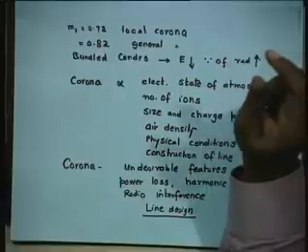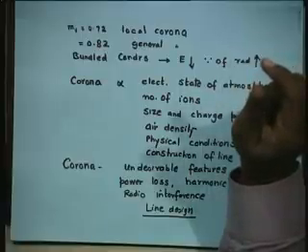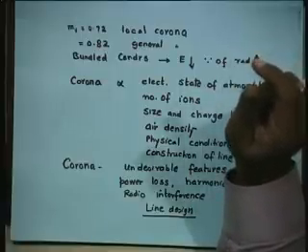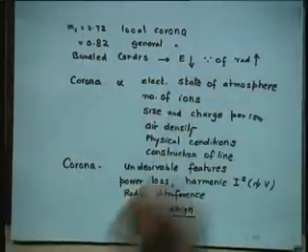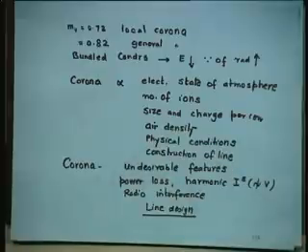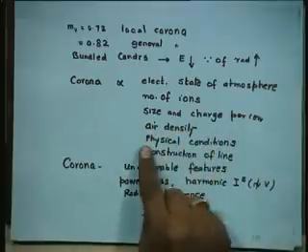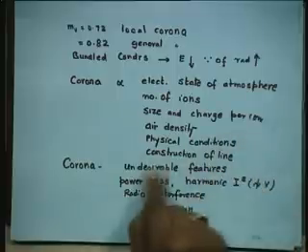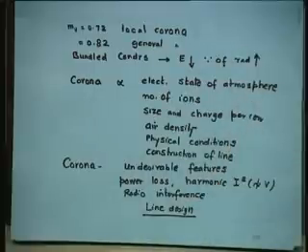Why do we use bundle conductors? If you recall, one of the answers we gave for using bundle conductors is to reduce the chance of corona, because the electric stress goes down and therefore the radius goes up. Electric strength decreases. Corona is proportional to the electrical state of the atmosphere, number of ions, size and charge per ion, air density, physical conditions, and construction of line. These are all the factors you have to mention the moment the question is: list the factors on which corona formation depends.